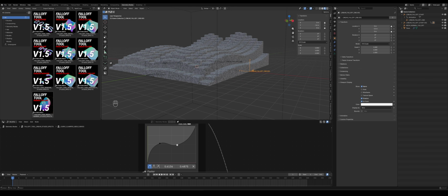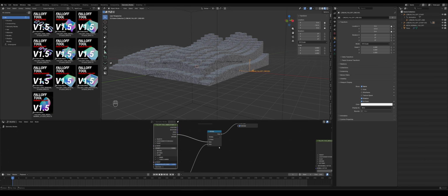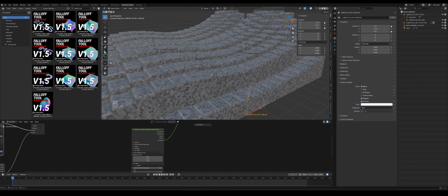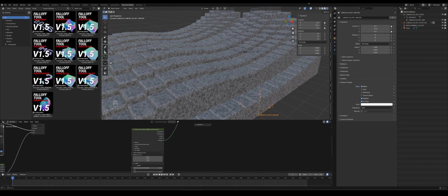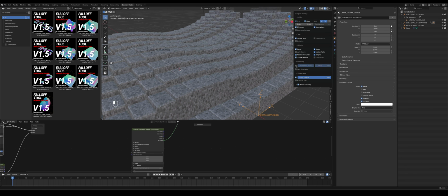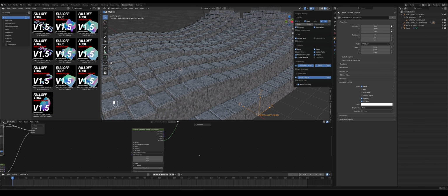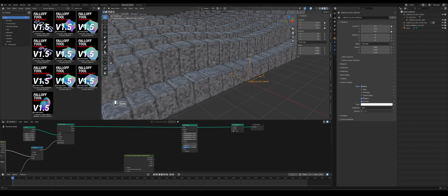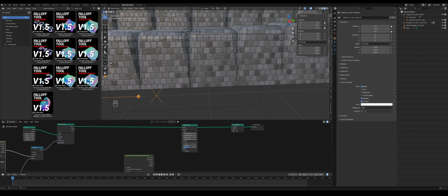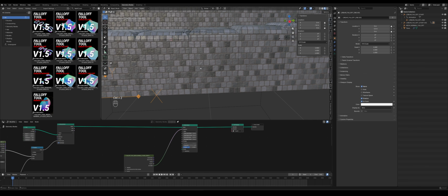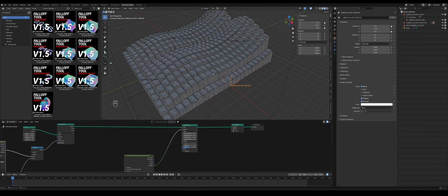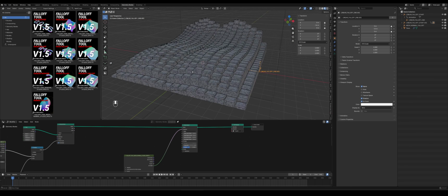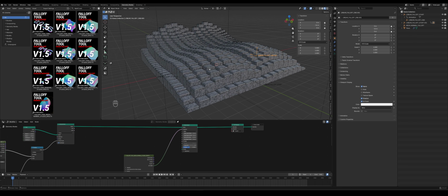And the normal falloff, which I just demonstrated, to filter that bevel, which only bevels the top of this set of steps. And if we disconnect that, everything is being beveled, so even the corners. So we get these weird corners here. I don't like that, so that's why I use the mesh normal falloff to create a more coherent look that makes more sense for a set of steps.